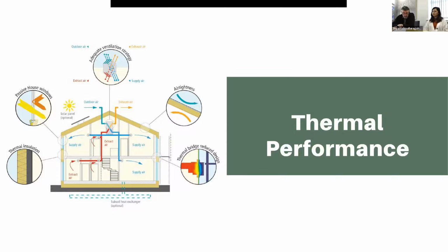Thermal bridging, where you have a highly insulated fabric, but the junctions of floors and walls, windows and walls and so on are now susceptible and can lead to mold risk if you have warm surfaces or cool surfaces that all of a sudden have a weak point in them. It's something that needs to be looked at.